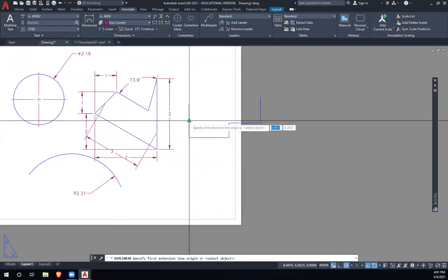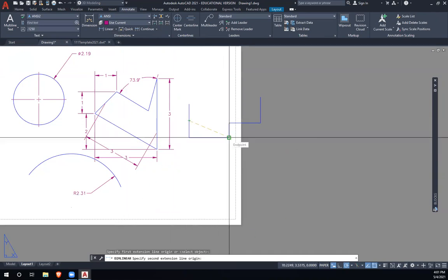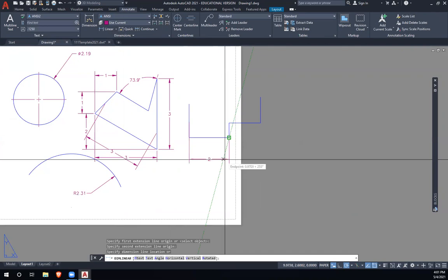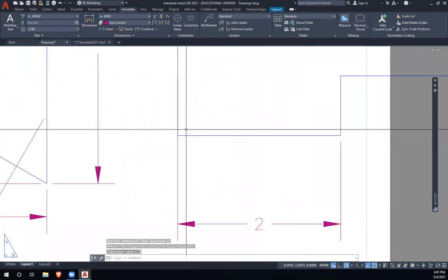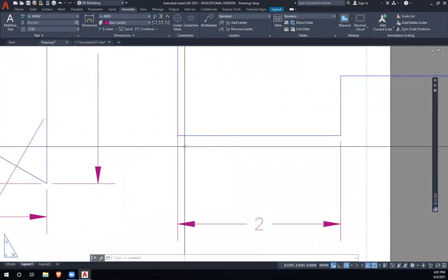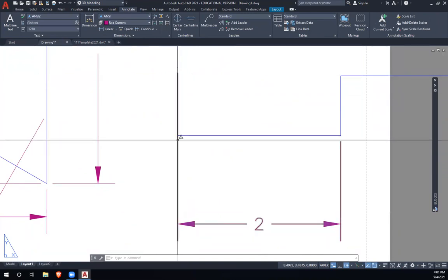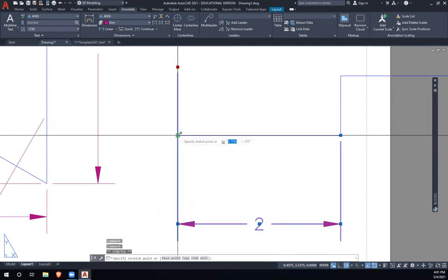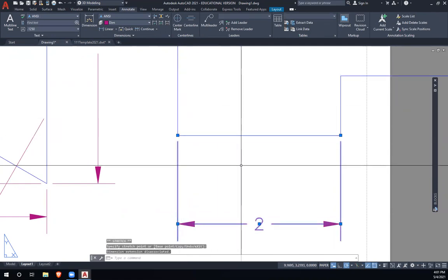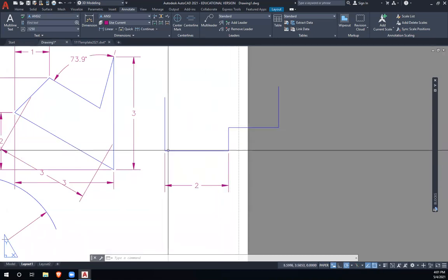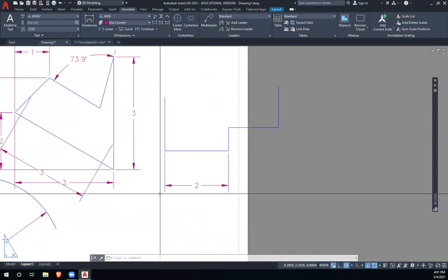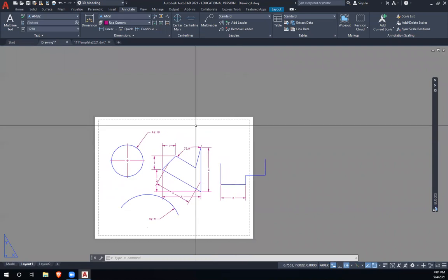If I click from here to here, it's just going to give me a horizontal or a vertical dimension. And see how if I didn't click on the corner, that dimension line just covers up that gap. That's supposed to be there, or that offset, right? So move that back down. And now that's how it's supposed to be. You'd be surprised how easy it is to remove that gap by not getting on the corner, right? So be aware of that while we do it.